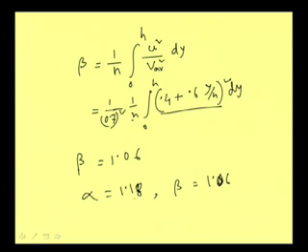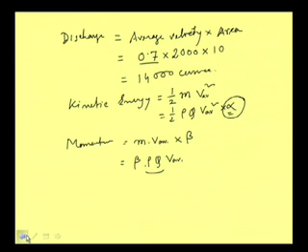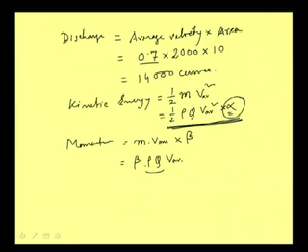So, what we have seen is that the alpha value is 1.18 and the beta value is 1.06. That we discussed in our last class, that alpha is greater than beta is greater than 1, and we have seen it in actual calculation. Now, if we go to our earlier slide, if we calculate this kinetic energy by simply using this formula, then it will not be complete. Rather, it will be less by 1.18 times.